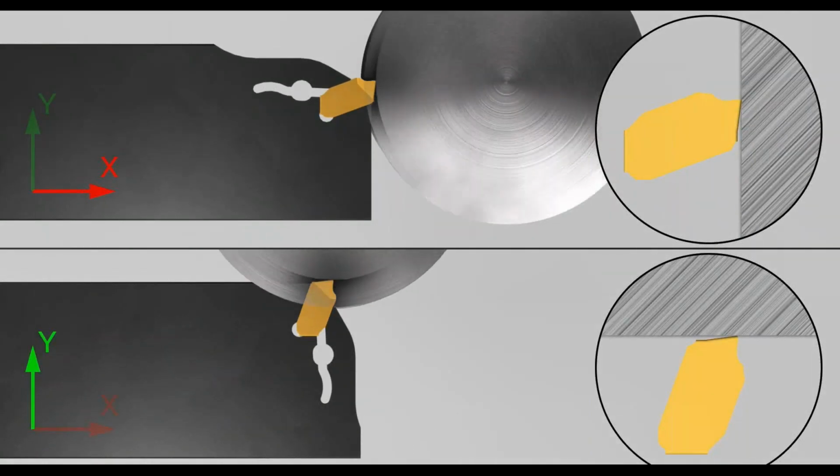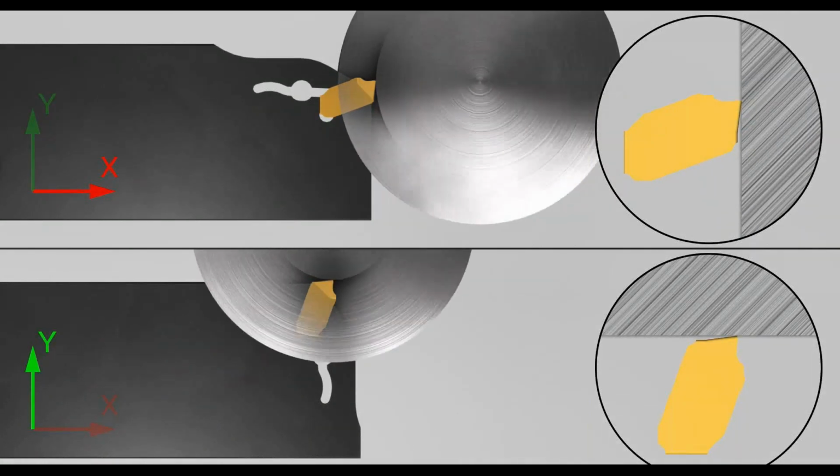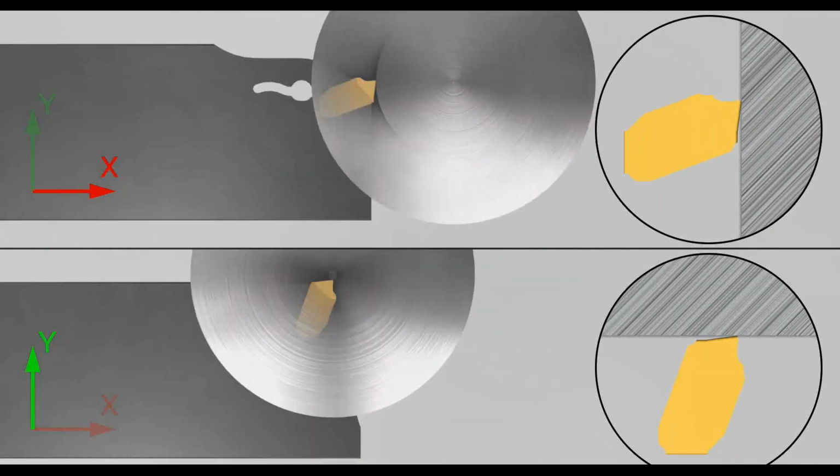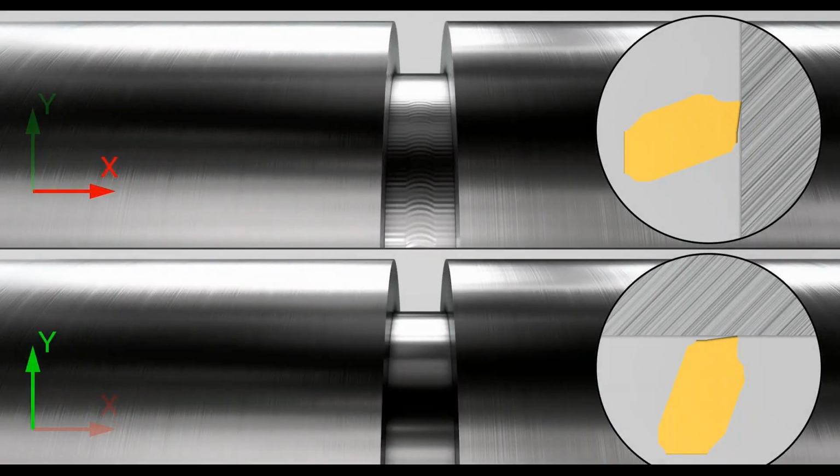Now, changing that position of the blade gives us multiple things. It gives us more rigidity, which means now we can actually do larger bar and have that sticking out farther. Reduces vibration. We can actually pick up the feed rate, and we can have a better quality part off when we do this.